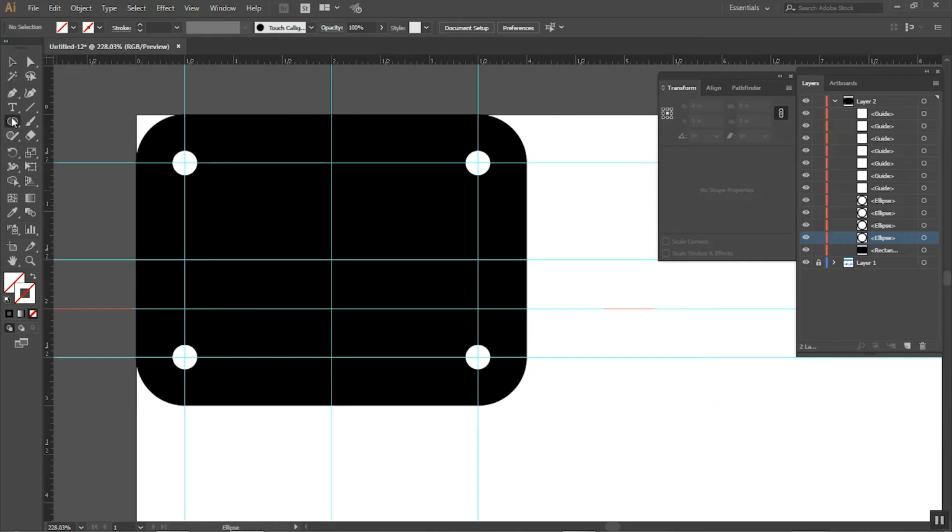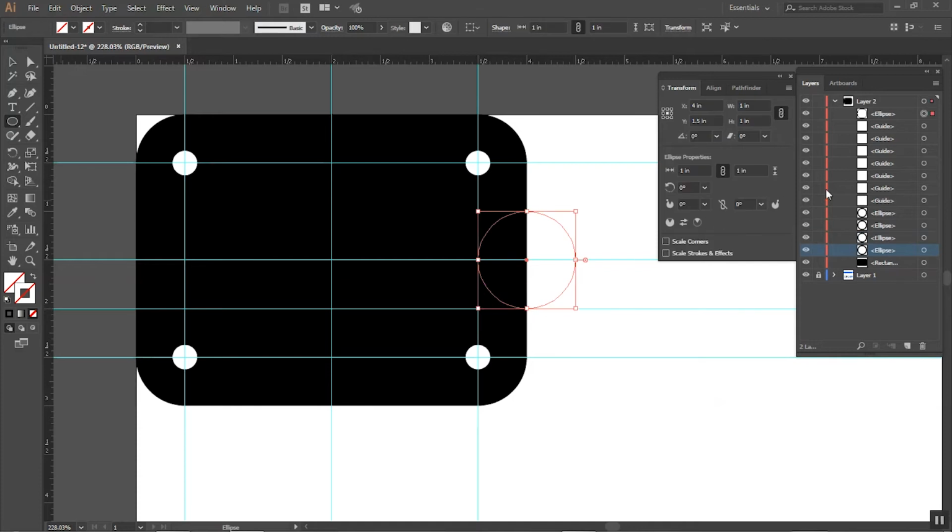So now I'm going to create a circle over here for that little notch in the side. So it's centered here. It's 1 inch diameter. So we know that this is ½ inch. So if we align with that, we should be good. So we get intersect at that point. If I hold down Alt and Shift on Windows, I can now intersect at that point.